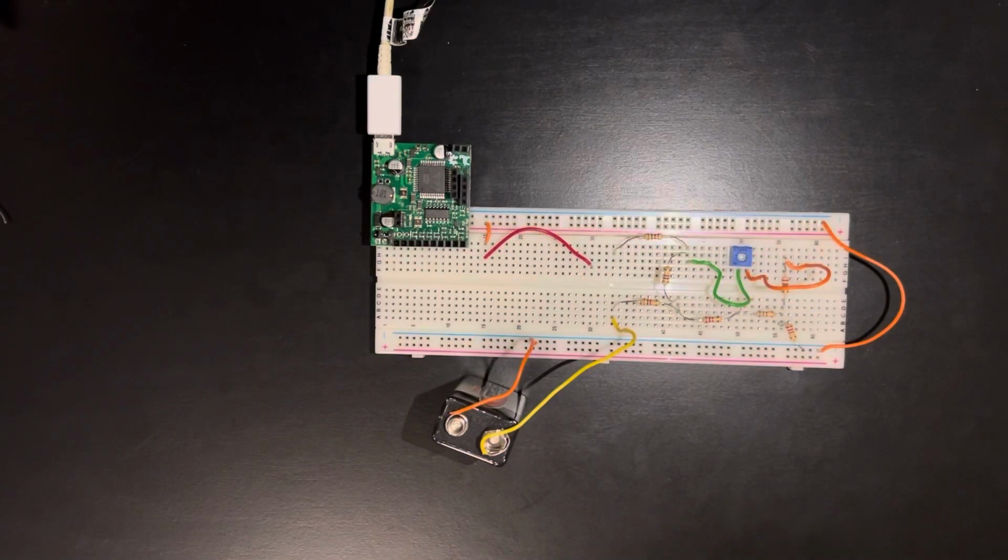Now for Kirchoff's voltage law verification, which is table 2, there are 2 loops mentioned. One is 0-2-4-6-5-3-1-0, that's kind of like an inverted L-shaped loop. And then another loop mentioned is 6-4-3-5-6. There are other loops, like you see in the third column of table 2 that says your loop. That means you can take any other loop into consideration apart from these 2, and then you have to verify Kirchoff's voltage law.